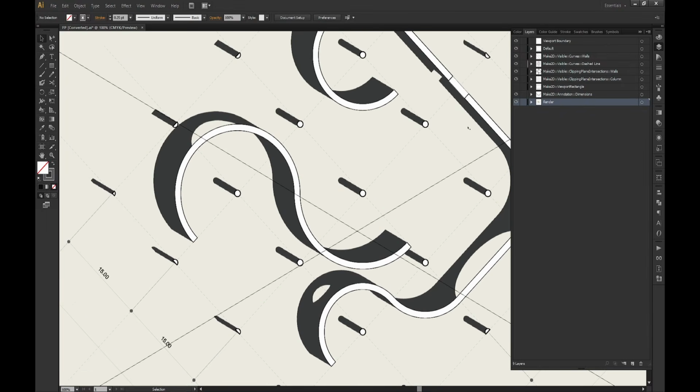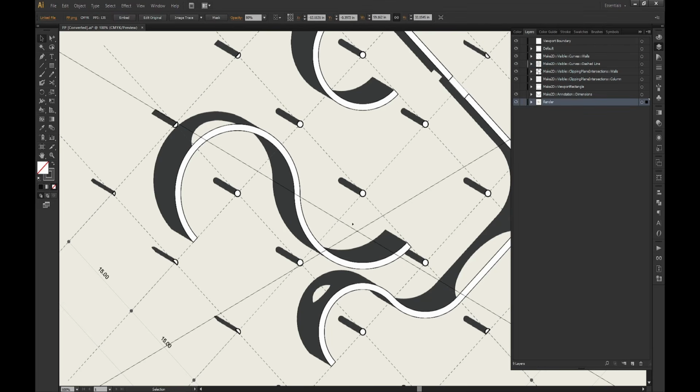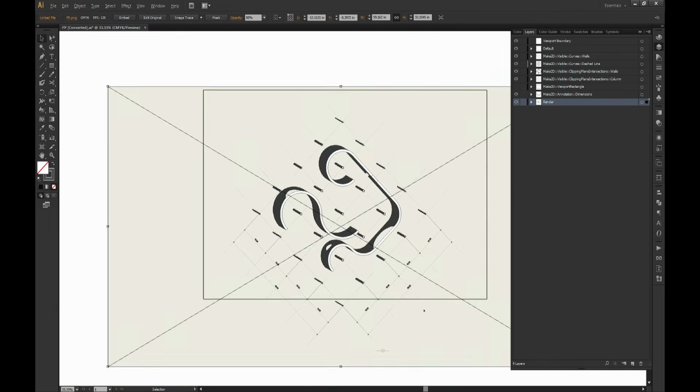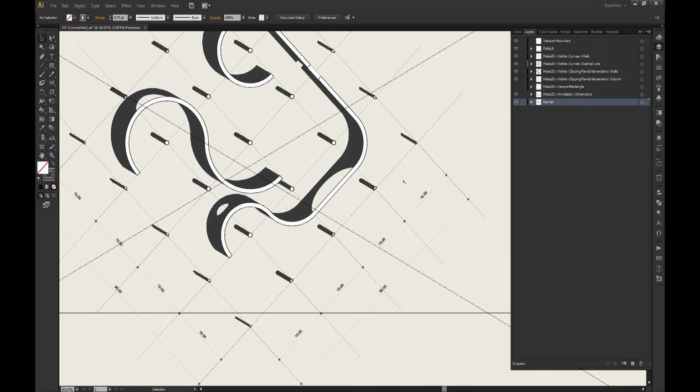So this is the floor plan with the drawings over it. The dash lines again look really light because of my screen. If I make them really heavy just to exaggerate them, I'll make it like 0.75, just so you can tell. There you go. You see? So that's basically how you get your shadows into your floor plans and from Rhino into Illustrator. It's a very simple process.